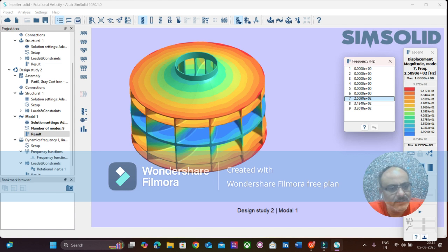And in the episode before that, we dealt with structural simulation, where we applied the proper boundary conditions. We have also bolted the system, and we applied a rotational velocity at the center, assuming that there is a shaft which is rotating at about 800 rpm. And with this angular velocity, it exerted a certain force, that is the pressure force. The internal kinetic energy of the air from the shaft end is converted into pressure energy, and it is radially distributed from the exits.